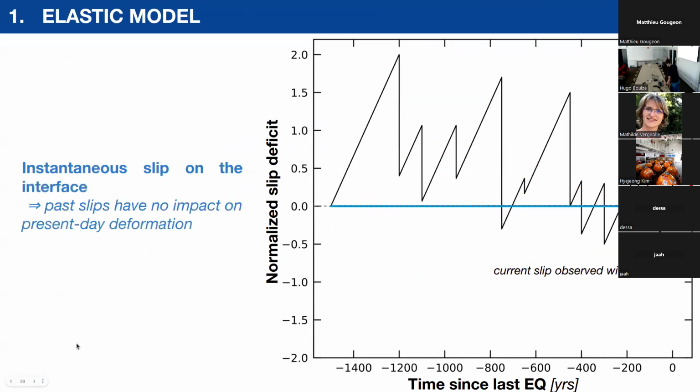Yeah. So how I model it. Instead of your model, you apply a co-seismic slip distribution. So you have a displacement between two groups of nodes along the fault plane. And you can mimic the seismic cycle, but it costs lots of computation time. So in terms of numerical approach, you impose your co-seismic slip at the beginning, and you let your model evolve for a very long period of time.